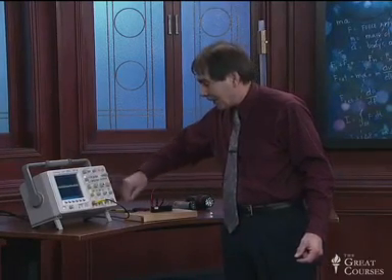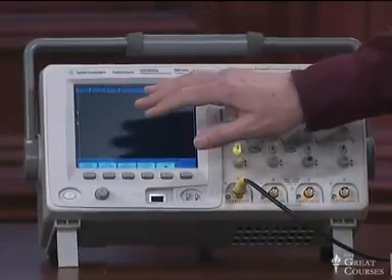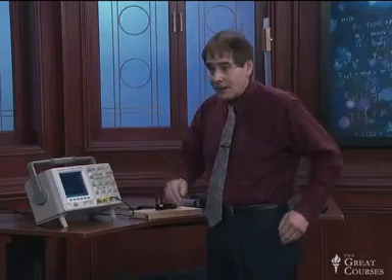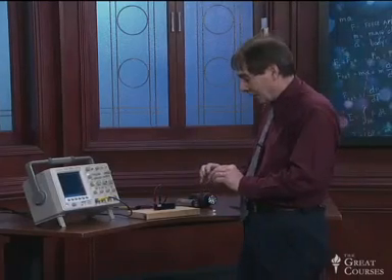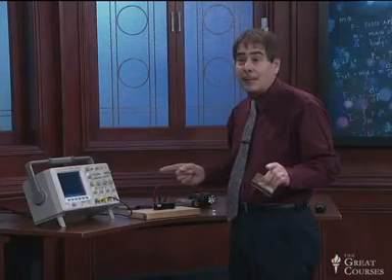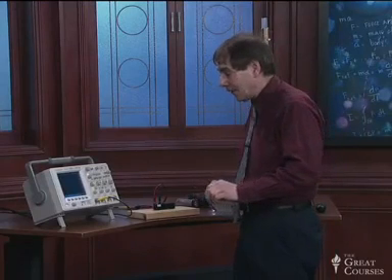I've connected this through a cable to this oscilloscope, which we will use to display the voltage that is induced by the card. So we're ready to go. We'll also look at that on the big screen. I've got the oscilloscope set to trigger off the induced voltage. We're in a very noisy environment here in the studio, so the results are going to be very noisy, and occasionally it triggers by itself off the noise.